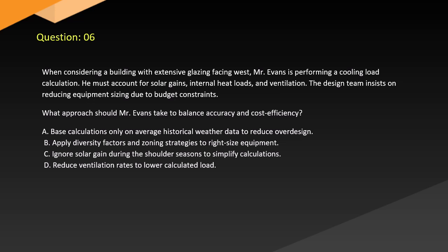A. Base calculations only on average historical weather data to reduce over-design. B. Apply diversity factors and zoning strategies to right-size equipment. C. Ignore solar gain during the shoulder seasons to simplify calculations. D. Reduce ventilation rates to lower calculated load.